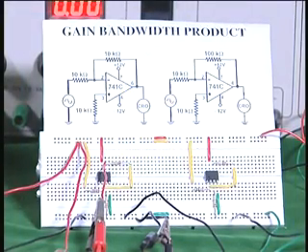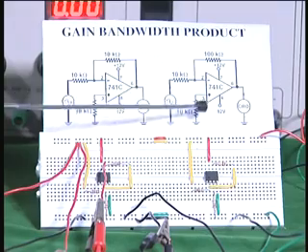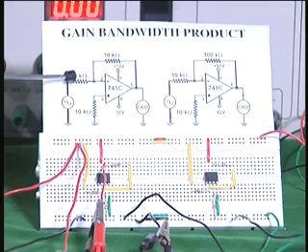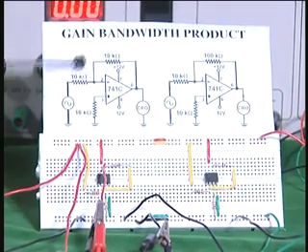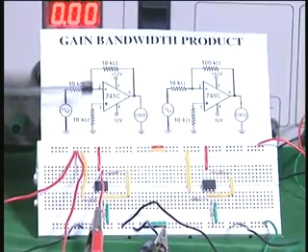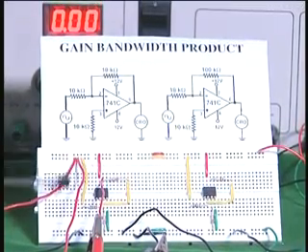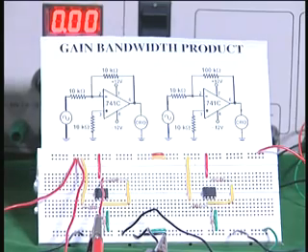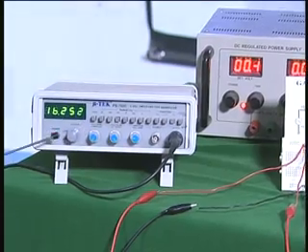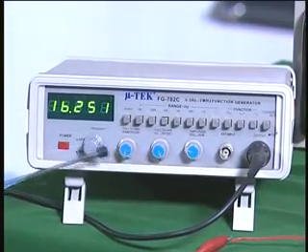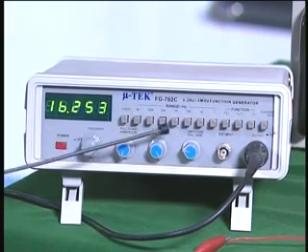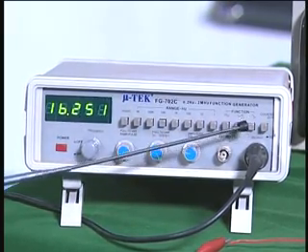So we have again the breadboard with the two circuits simultaneously shown. This circuit has a 10k in the feedback and 10k at the input. RF by Ri is equal to 1. So this is an inverting amplifier with a gain of 1, and that circuit is shown here at the bottom in the breadboard, and the input is connected from the signal generator, which is again the sine wave oscillator. You have the amplitude variation here and the frequency variation here, you have frequency multipliers here, and I have used the sine input here.